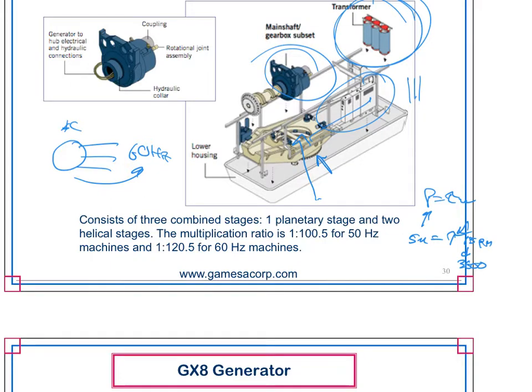So that's the disadvantage of what's called an upstream horizontal axis wind turbine: it has to be oriented in place. If it's a downstream one, it auto-orients. The downside of that is now you have the tower slowing down the wind on a portion of the blades impacting it. So most of the commercial turbines that are larger scale almost always have upstream and they just rotate like this. It will position itself, and it takes a while because it's not something you want to be changing constantly, but it does work.